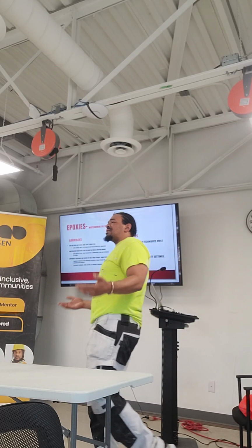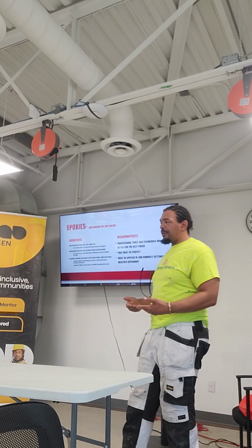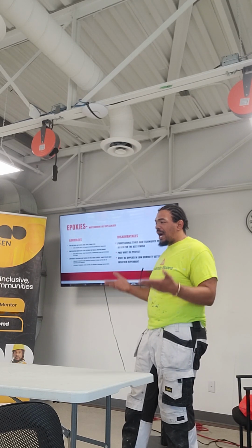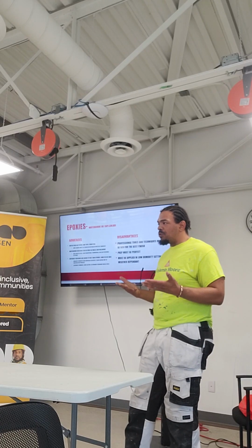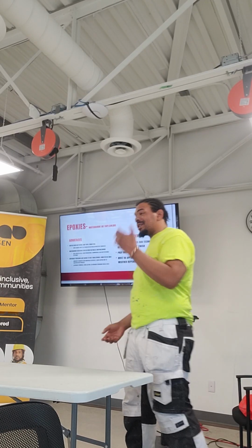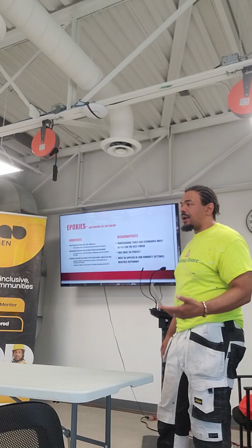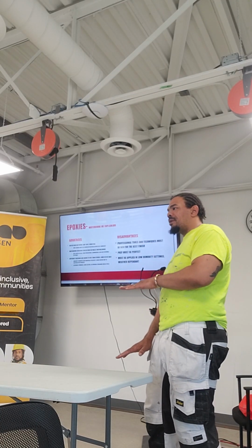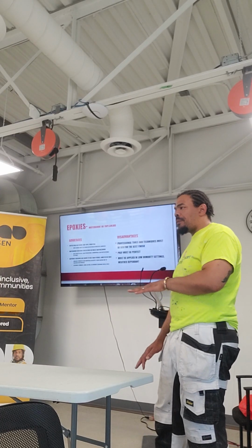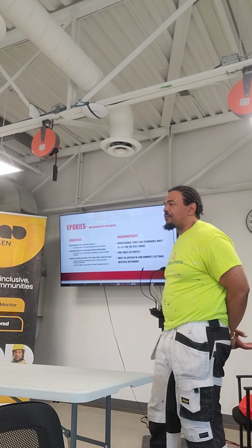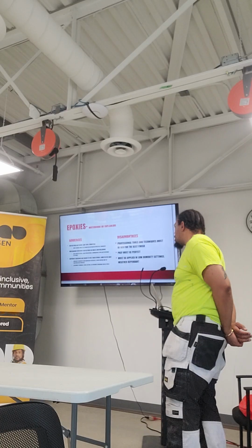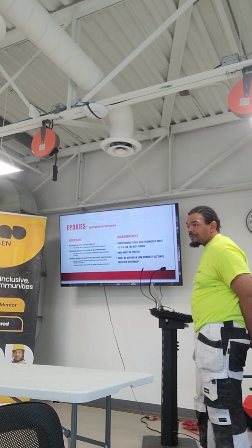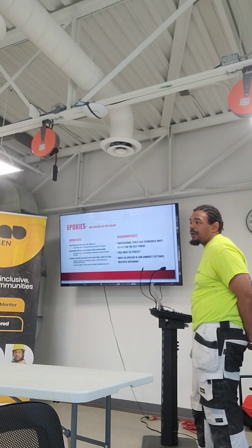That's why houses have to settle for a few years after they're built, right? You have to let all of the water and sediment dry out, and then the house settles, and we're not worried about anything moving after that. But in those cases, we use a vapor barrier primer, which creates a barrier so it doesn't allow moisture to come up through the concrete from the groundwater. It's 100% solids, and it works very, very well. We've used it a few different times and had great results. It's expensive, but you get what you pay for.